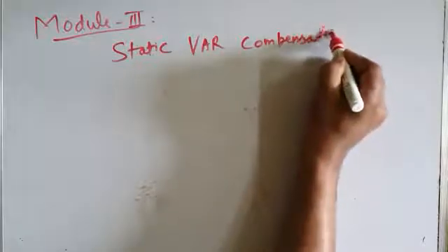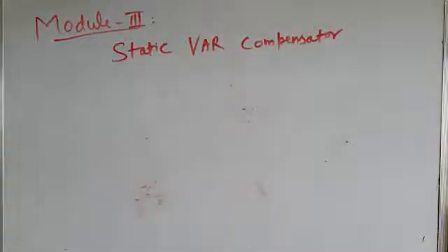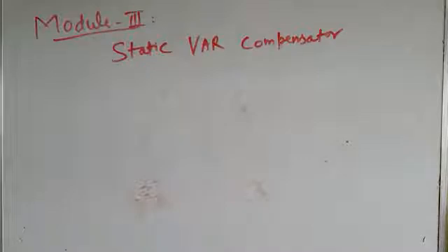Now, I have already given you the idea about a static VAR compensator. It's basically a shunt compensator which exchanges reactive power with the system bus or with the transmission line, and hence it results in various advantages, like it increases the power transfer capability of an existing transmission network.